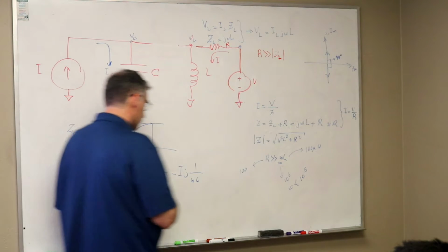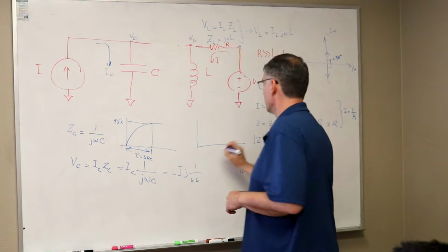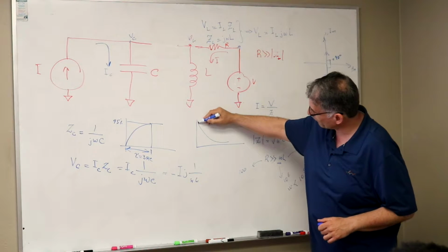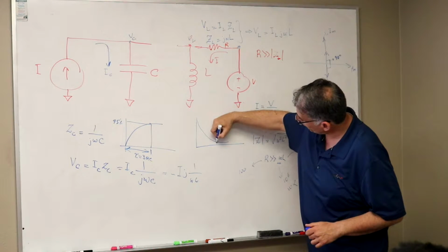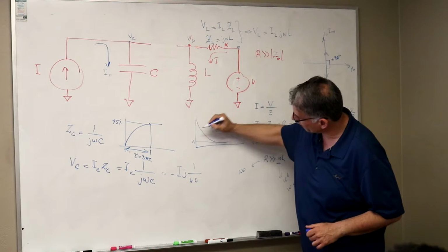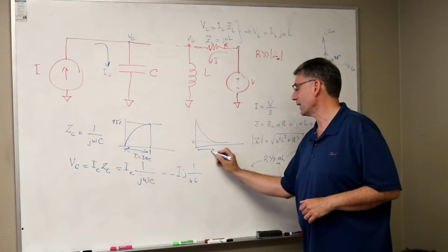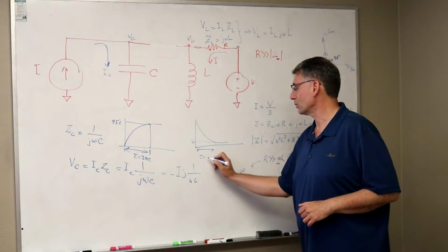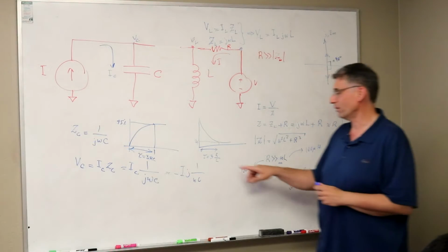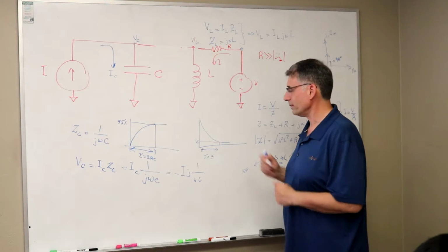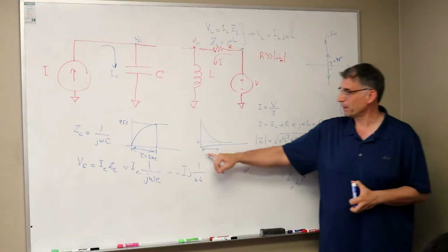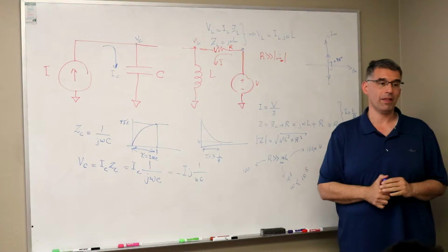In the case of an inductor, the voltage drops like this, and so we look at when it drops by 95%, so this would be at 5% of the max, and then again we would take this time, and this was equal to 3 L over R. Again, we measured it, and then we could figure out what L is based on that, right?